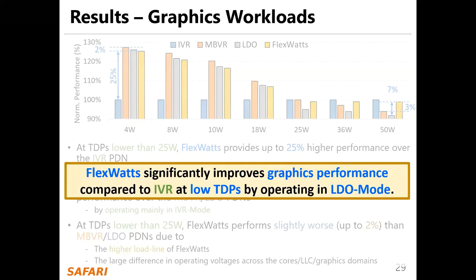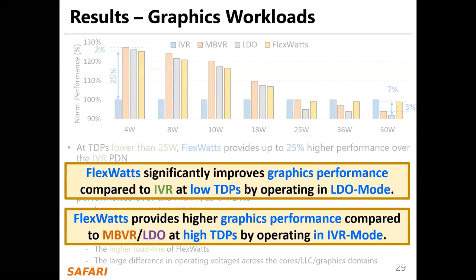We conclude that FlexWatts significantly improves graphics performance compared to IVR at low TDPs by operating in LDO mode. FlexWatts provides higher graphics performance compared to MPVR and LDO at high TDPs by operating in IVR mode.